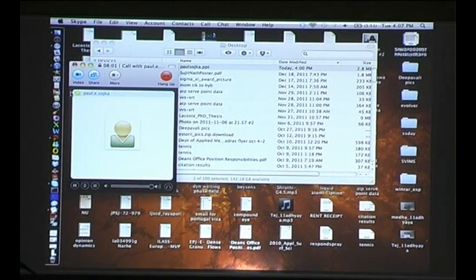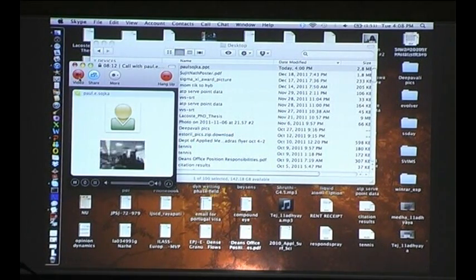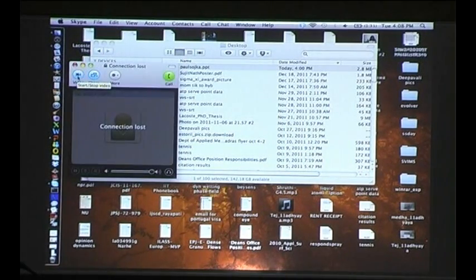All right. So here we have the bag breakup mode, which is the lowest Weber number range of all the practical modes of interest. It's called the bag breakup mode for obvious reasons. We have a cross-sectional cutaway view here on the right that shows the drop deforming into a bag with a thickened rim at the upstream edge. The bag and the rim break up into different sizes because of the different characteristics of the two parts, and so you often get a bimodal distribution.